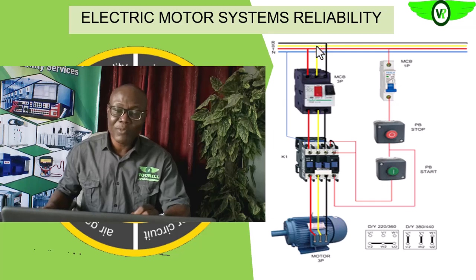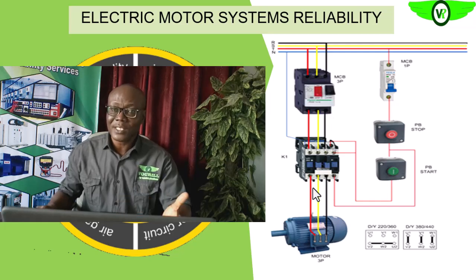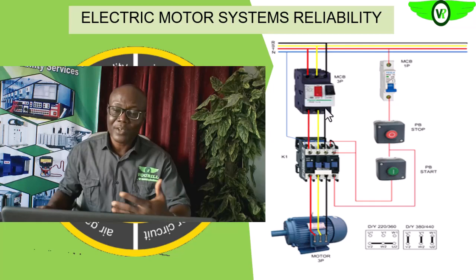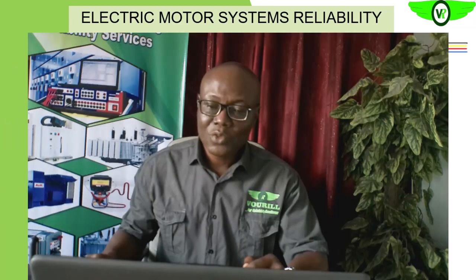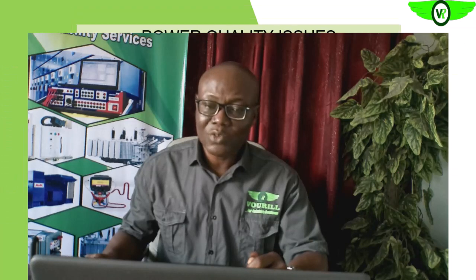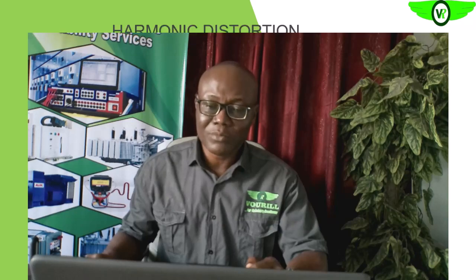If it is not coming from the power supply, it can come from these lines, as we will see later, because of resistance build-up. So it is very important for us to maintain balanced voltage to our electric motor.